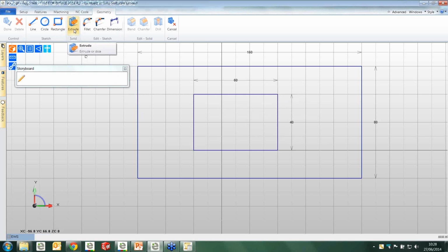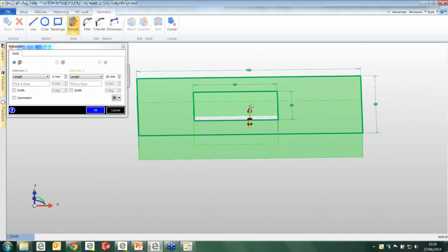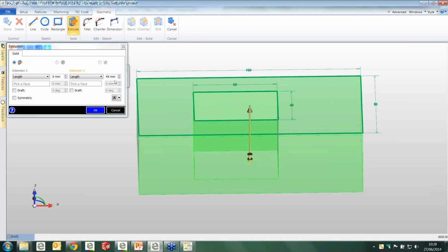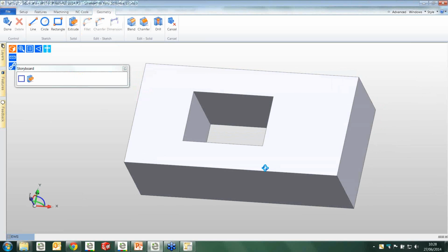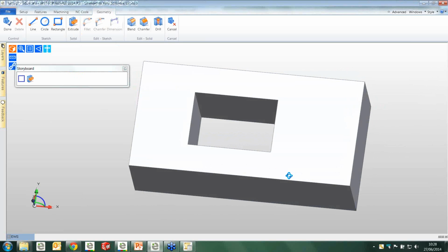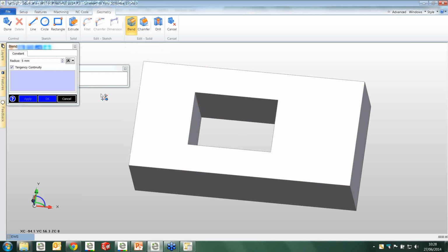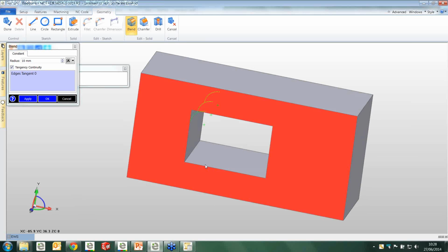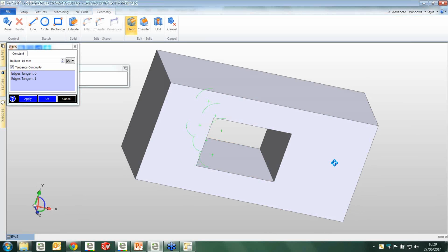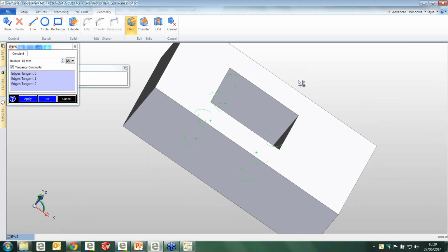And we can turn that into a solid model simply by extruding the part. We can drag and drop to influence the size, or indeed we can enter a user value of 50 millimeters here. And very quickly I have a solid model created. For the pocket, I wish to consider the sharp corners by adding a blend. So here we can add a 10mm blend, for example. We can move around the part, selecting each of the corners, adding the fillet blends.